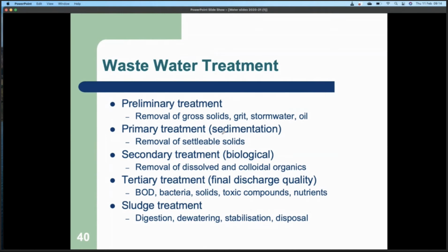And then you have the sort of separate process almost of sludge treatment. So if you think of the sludge that comes off a sewage works, as it comes off the works, it might have something like 8% solids. So the sludge is primarily water, 92% water or thereabouts. So the first step normally is that you dewater it, you reduce the water concentration, so you're not dealing with so much water, but you're dealing with the stuff that you actually want to deal with.